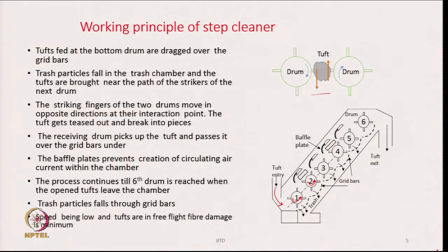The speed being low and the tufts are in free flight, fiber damage is minimum here also. So, we are not gripping the tuft and then beating by any other striking elements. So, therefore, the opening efficiency is relatively much less, but the nature of opening is quite mild and gentle in nature.